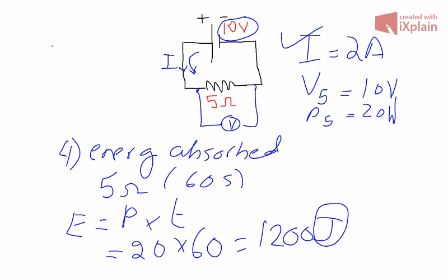And what the voltmeter essentially calculates is based simply again on Ohm's law, which will be current times the resistance, which will be 5 ohms times 2 amps, or 10 volts. And that is identical to the battery that's feeding it, because there is no other resistor in the circuit. So the entire 10 volts is being taken by the 5 ohm resistor. So the voltage across a 5 ohm resistor is simply 10 volts.